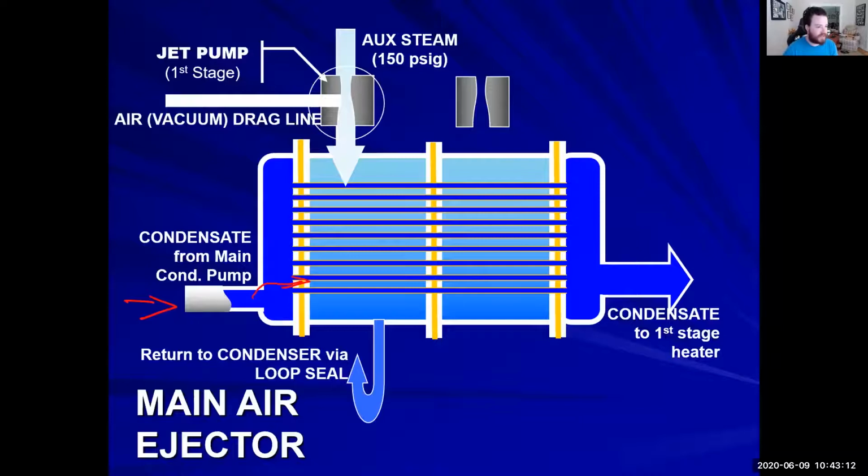This is what is physically happening inside. We are using auxiliary steam, and that auxiliary steam is going through a nozzle. That nozzle has a Venturi effect. Remember, it's going to be sucking in and pulling whatever it's attached to. This is technically that low pressure over here. Here's your high pressure. And that low pressure is getting sucked in no matter what. Whatever is in that line, whatever is in that main condenser, is going to be sucked in, and that's how you get that low, low vacuum.